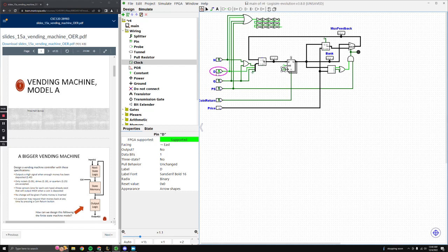But if we do it off and on super fast, the inputs will not register. So if anyone were to enter a nickel, a dime, or a quarter at a positive clock edge, their money would be eaten, leading to many problems. So having a clock on the actual input itself is not necessarily the greatest design.